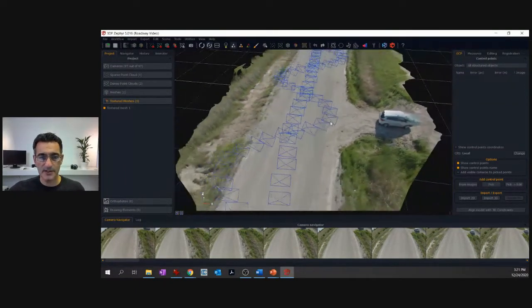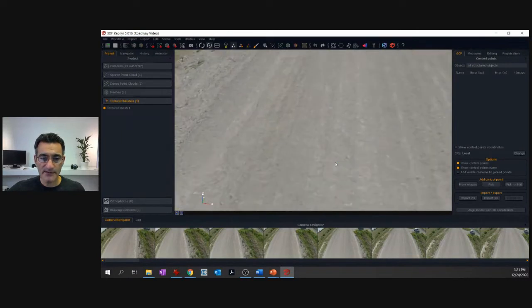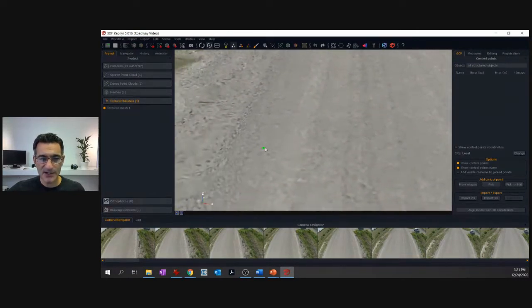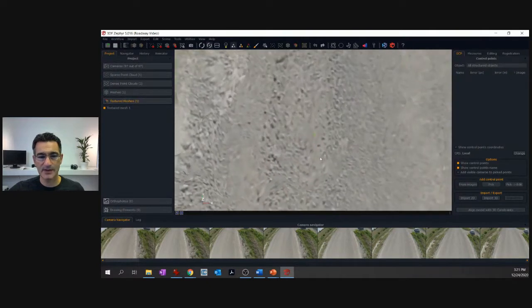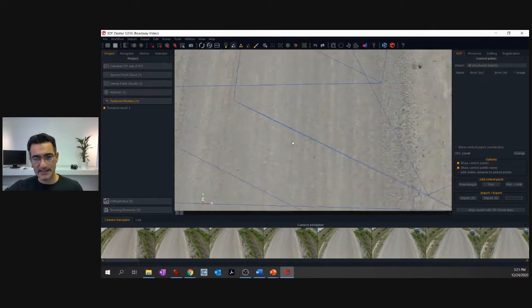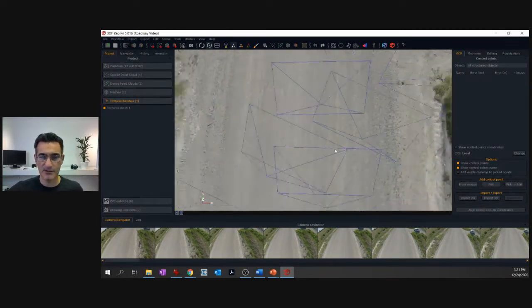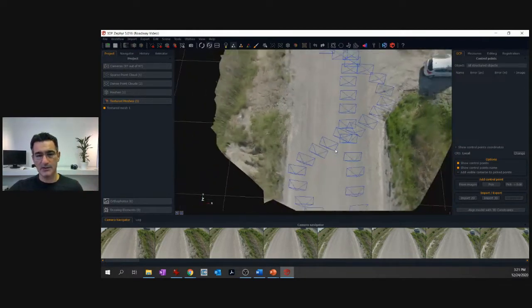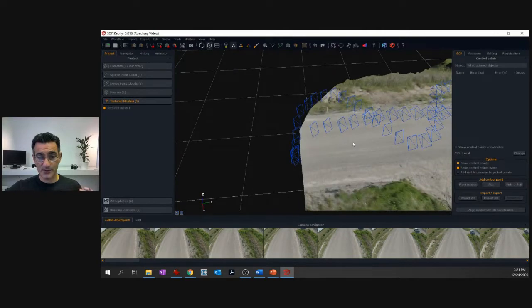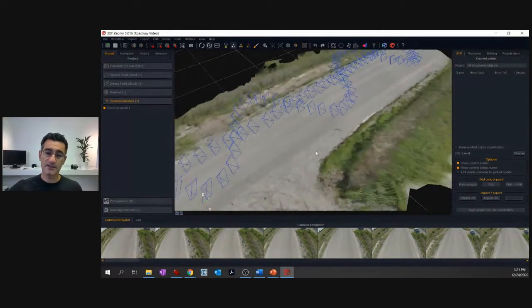So video is absolutely possible. The quality, if you go down on the roadway, you'll see that the texture is okay, but it's not great. Okay, it's not the best. And again, that's because there's a little bit of blurring when you get down to those fine resolutions. You're not going to get a nice crisp image. So if I wanted higher detail on the roadway, two things you could do with the video camera is get closer, move slower around a particular object or something that's on the ground, or switch to digital still. And if you have digital stills at high resolution, those are going to work out the best for you.